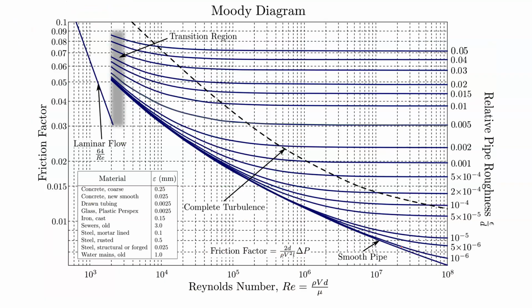Now for the first case, the Re we got is 1871. So this is the Re. Here is the line at 1871, maybe we are taking approximate values. This line is the laminar flow line, so that will cut here. Then if we go to the left-hand side along the horizontal line, it will cut here, and that will give the friction factor. So for Reynolds number 1871, from the Moody diagram we get a friction factor of 0.0345.